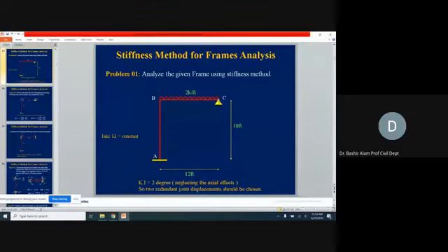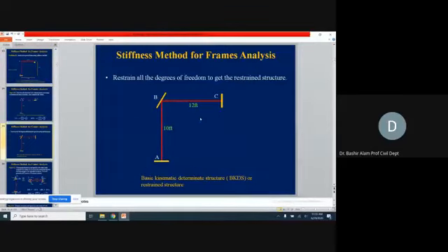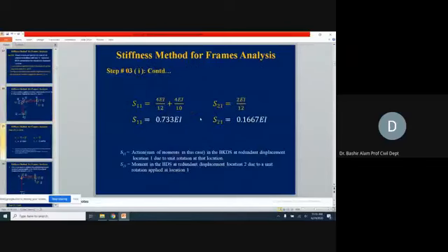So if we draw a tangent now here to the deflected shape, it means it is counterclockwise, it is not clockwise. So at C, now the member will deflect. If we draw a tangent to this, it will be in the counter direction. What we assumed in the previous case, we assumed that it is deflecting in this shape in clockwise direction, but it is not clockwise. And the final answer is now telling you that your original was wrong. So what we do, we just reverse the direction.